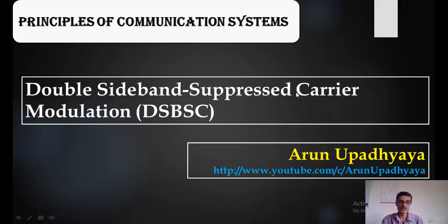Now, what is the advantage of suppressing the carrier? I think I might have told in my previous videos that we save a lot of power. That means the transmitter does not have to generate any high power here. We can save up to 66.66% of the total power by suppressing the carrier. So that is the advantage of double sideband suppressed carrier.